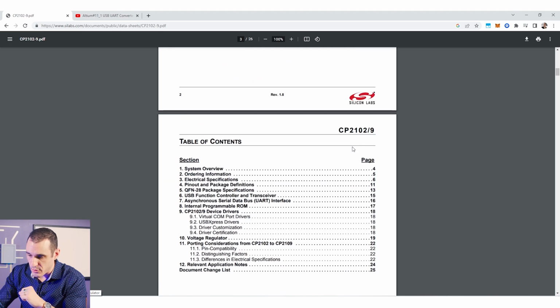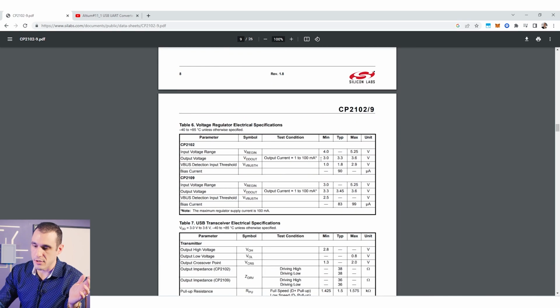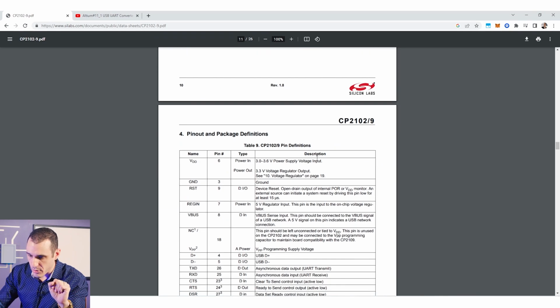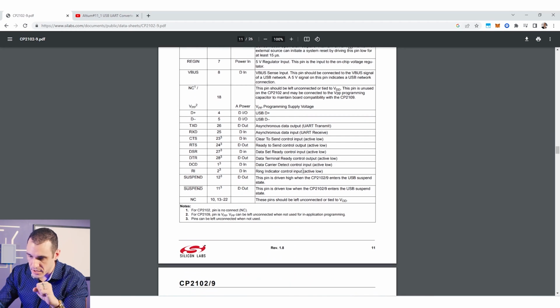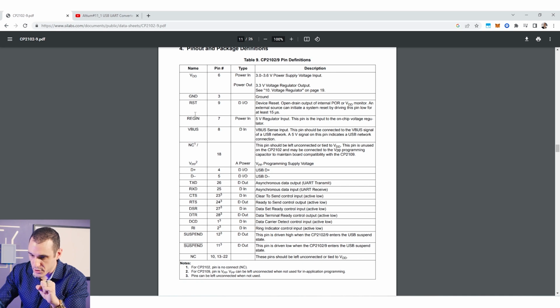In the datasheet, we want to look first at the pin descriptions. And of course, you can reverse engineer a lot of this if you have a module that already uses this chip. But what we want to do is go down here to the pin descriptions. First, which pin description do we care about first? Well, first we care about the V-bus voltage. We see that this is a 5-volt input signal from the USB connection. It says it right here in the pin description.